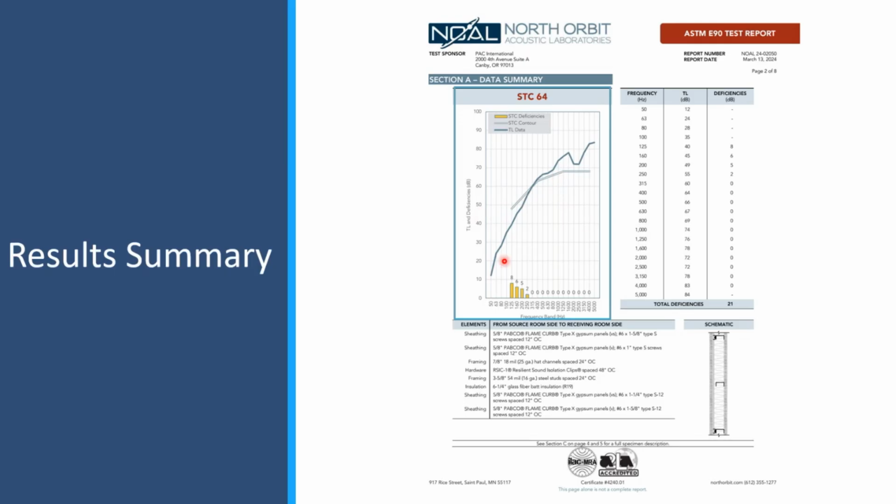So it's nice to see this as an acoustician looking at this. It gives a lot of information. You can quickly see from this picture how well it's doing at low frequencies and how it's doing at high frequencies. Here's this dip. This is a coincidence dip. That's typical behavior of drywall. You can see these kinds of things. Just helpful information to see.